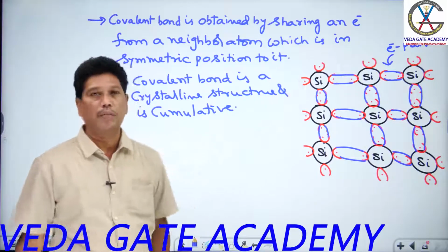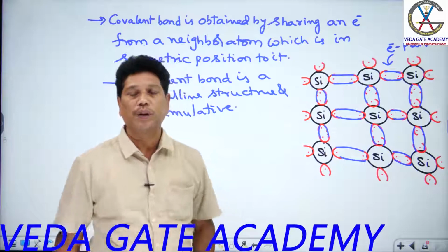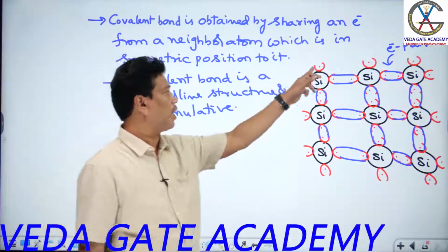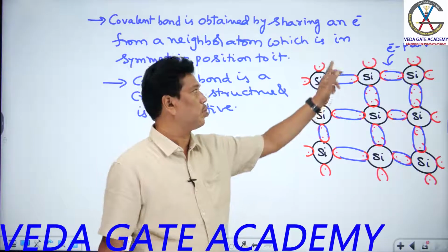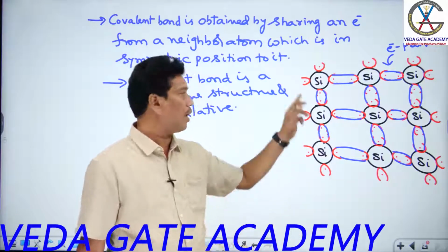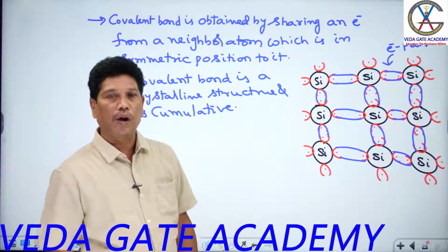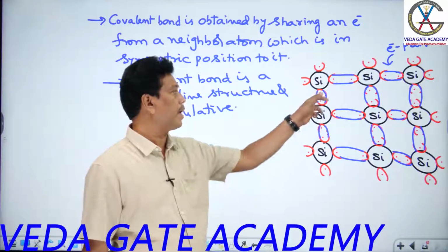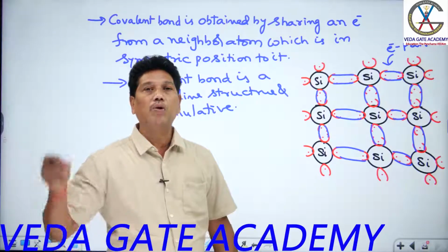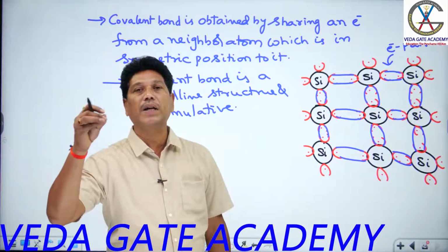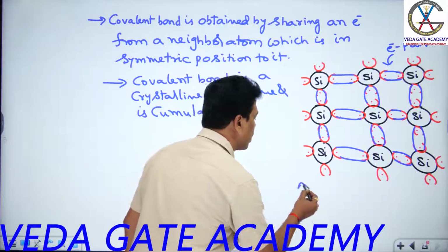So this is the structure. Sir, to this structure, suppose I don't apply any energy source. Without any applied energy source, no electron is free, students. No electron is free means it acts like an insulator. When do you get the electron free, sir? By breaking the covalent bond. How to break the covalent bond? By applying the required energy. That required energy is equal to the energy gap.